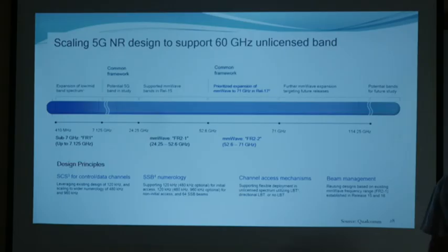Yeah, sub-6. In LTE people call it sub-6 gigahertz, but in 5G they call it frequency range 1. FR1 is a good frequency. It can go kilometer range, etc. So that is the big macro cell, supported by FR1. And the very, very small cells can support FR2, millimeter wave frequencies.